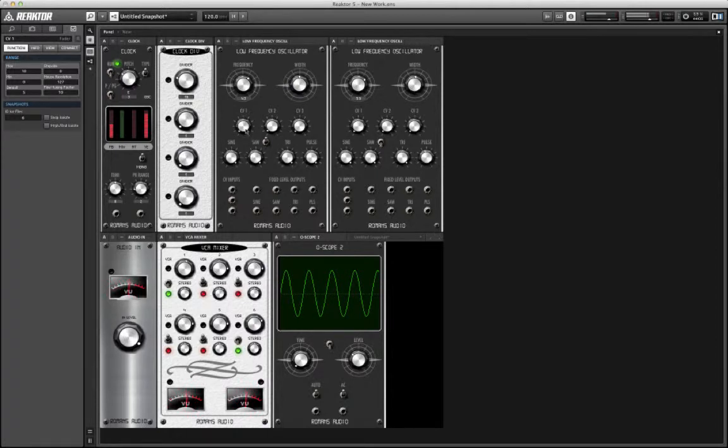As we go in, there's our standard sine. Now, here is our sine being modulated by the sine output of the second. Now you say, that's cool, but what do you use that for? Well, you run that into the CV for filter cutoff or all kinds of things throughout System 63. For right now, we're just concerned with knowing how to get to the different waveforms. Now, if you notice here on the second LFO, we have the saw inverted, so it's actually a ramp. Let's bring that ramp in a little bit here.